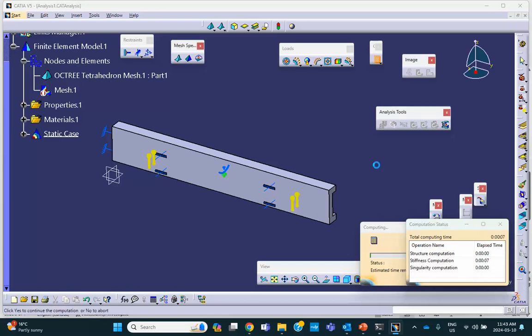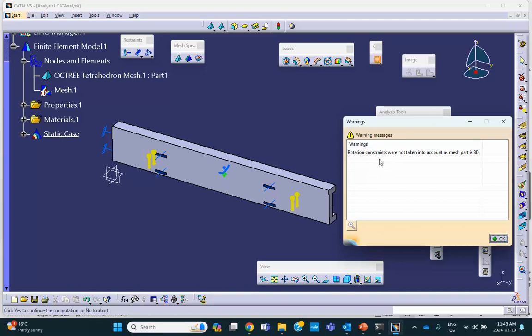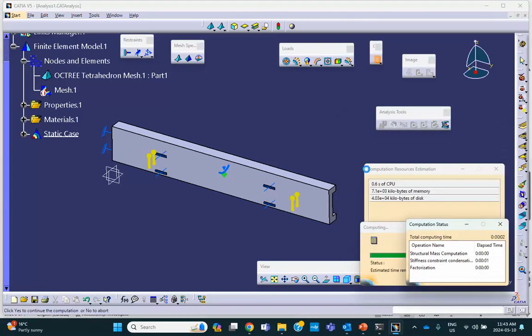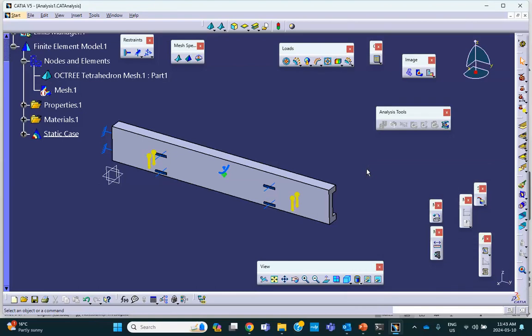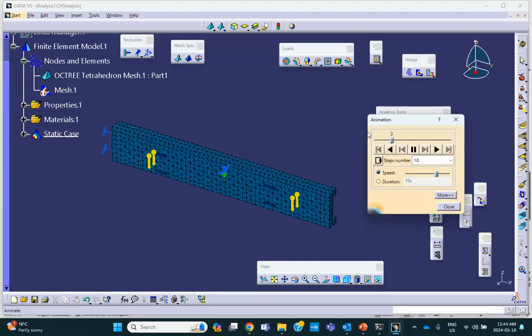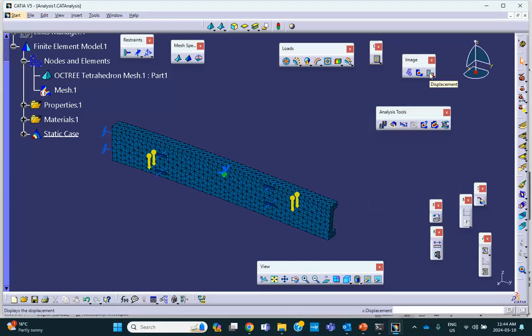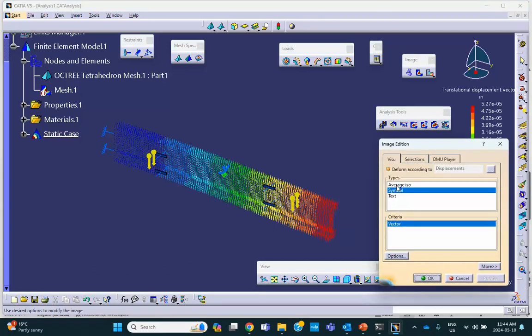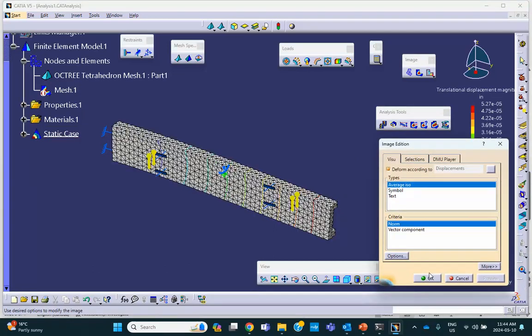Yeah, this is a warning that you get because you use surface slider. I don't like it, but they won't get rid of it. Okay, there. So look at the deflection, the deformed shape. There it is. That's the way it should be, right? If this is going under self-weight, that's the way it should be. And like that. If you want to know the value of deflection, displacement, just click on it. And this is in the form of symbols. If I want color, basically, select average ISO and change the rendering to material shading.